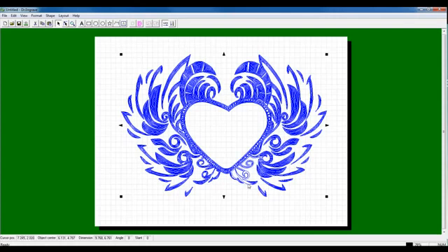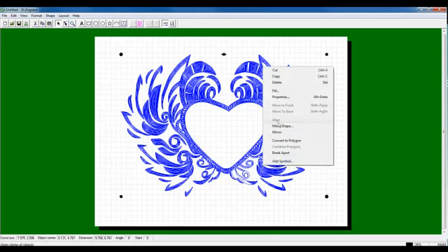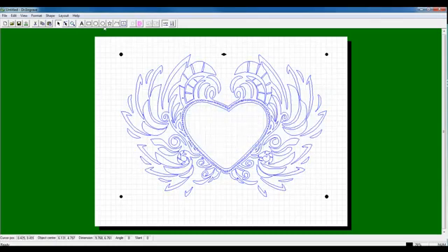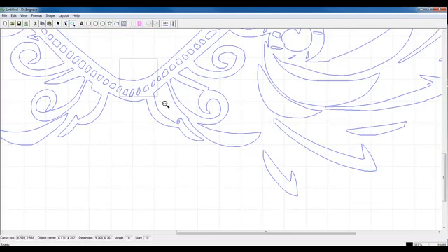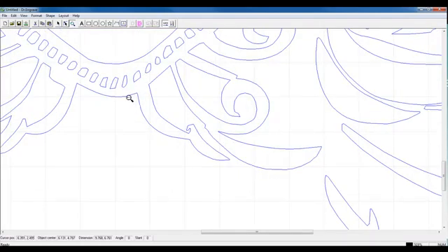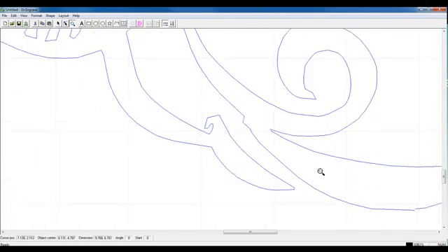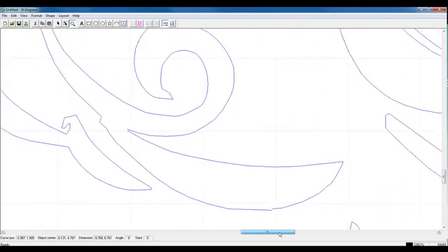You may have certain areas, as shown here, that did not get a fill. The reason for this is that there's an open connection in our graphic. I can go back to my fill, uncheck it, take my zoom tool, zoom into the graphic area, and look for that open node. As you can see, the open node is right here.